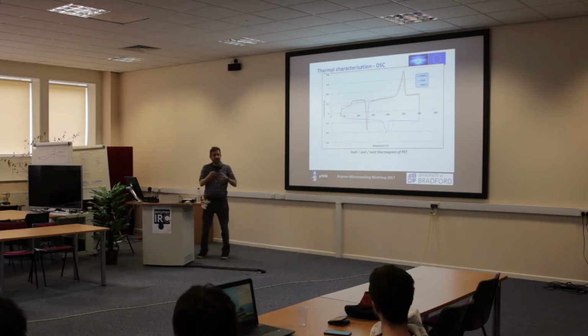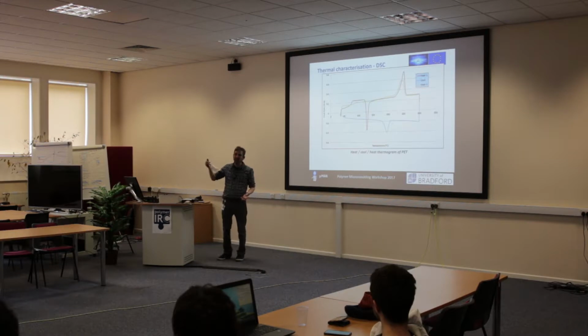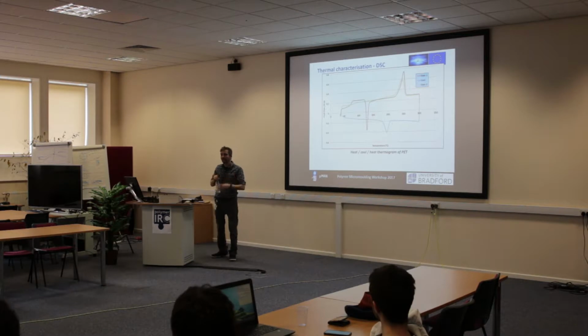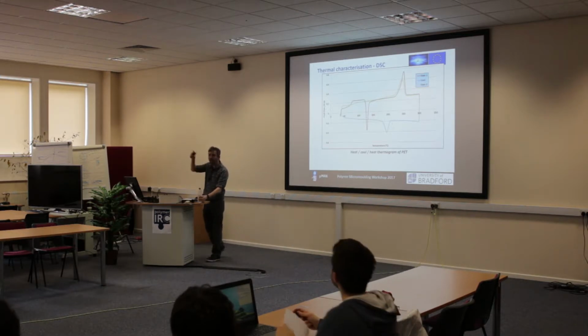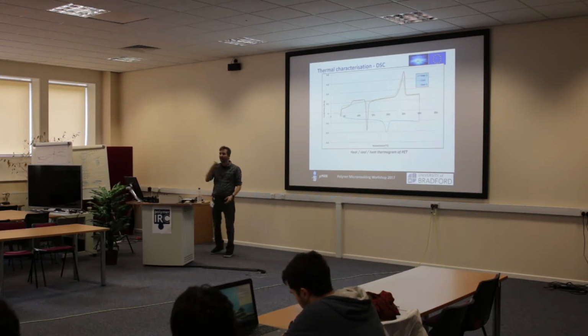And this is complex in terms of DSC, but it's fantastic for recycling, okay? This is why this bottle is made out of probably 99% recycled PET, okay? Because it's a living material. You can regrow its strength, okay? So there was a question yesterday, I can't remember who from, talking about recycling. If you send this stuff around a recycle route lots and lots of times, then you gradually make your material weaker and weaker.